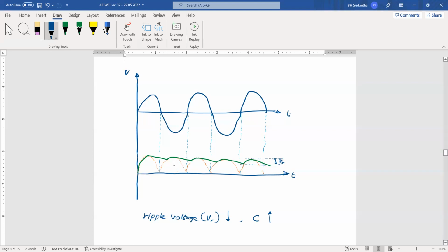So these are the things that we have to discuss with our applications. Now you know how to make a PN junction, and around the PN junction we have a depletion layer. You know how to break that depletion layer by providing voltage. If it is silicon, we have to provide 0.7 volts to break it. After that, the diode can conduct. We say it's forward bias mode. If you reverse the polarity, we say it's reverse bias mode. During reverse bias mode, the diode cannot conduct; you can consider the diode as switched off. During forward bias mode, you can consider it a turned-on diode.